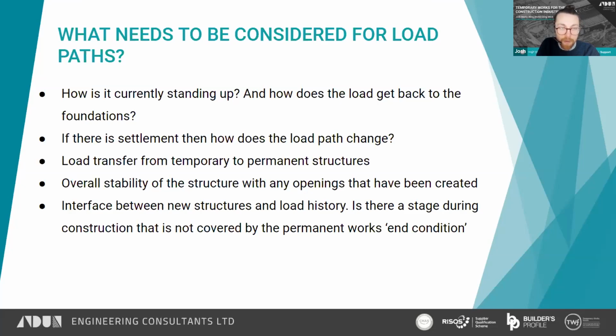The load transfer from temporary to permanent structures is very important and requires some thought and a sequence. The overall stability of the structure, taking into account any openings that have been created. Are we creating a structure that looks like a block of Swiss cheese? If so, we need to have a lot of confidence in the load paths, as there will be very little redundancy in the supports for that structure.